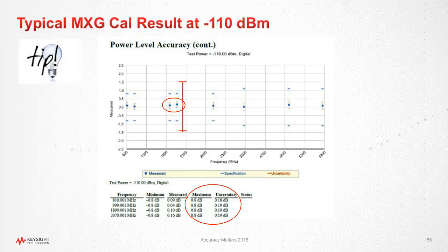So here's the last tip I want to give you. If one of your sources of error is, say, in a signal analyzer, you may very well be able to dramatically improve that error source by getting one of the new spectrum analyzers. In many cases, if you talk with your field engineer, they can provide a trade-in credit for some of those old ones. If I had your jobs and I was using one of those older machines with analog IFs, I would pound the door until somebody allowed me to get one of the new ones with the digital IFs.